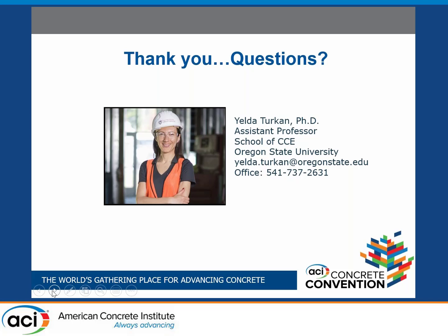Let's say there's a large equipment on the concrete slab that you're trying to scan and characterize the waviness. Obviously, you won't be getting any data points from there, right? So that is going to affect the results. So preferably, you don't want to have large equipment and workers being in the laser point cloud. We remove those during the post-processing, but they don't have a high impact in the results.